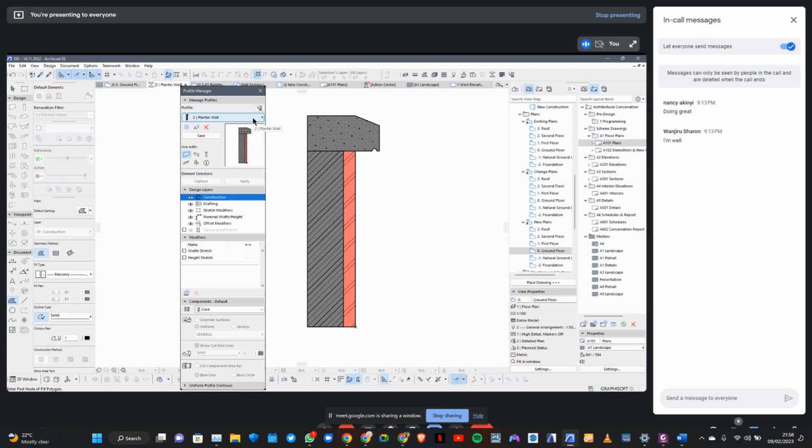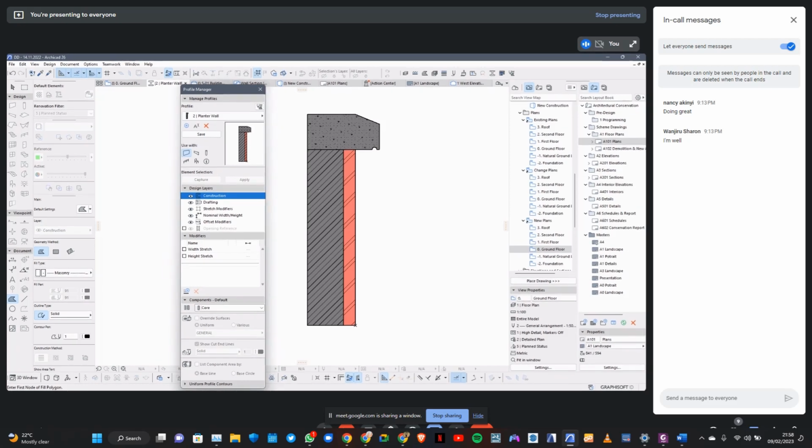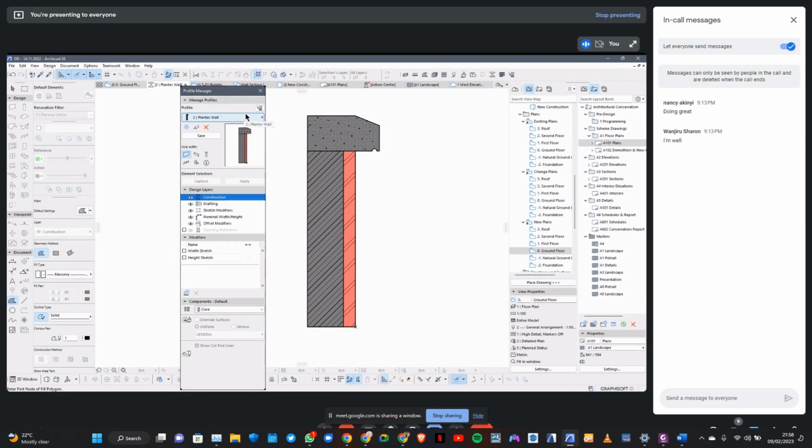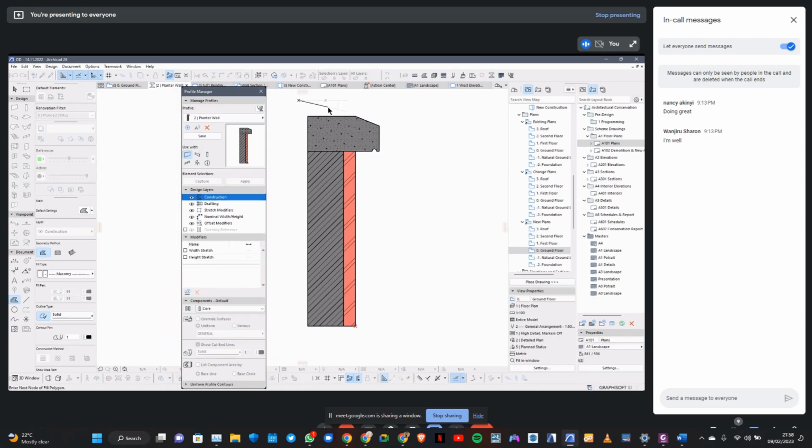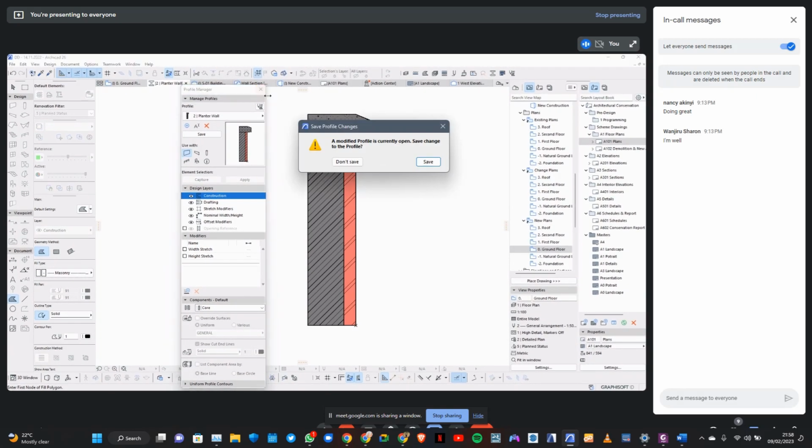I wouldn't want to model every single aspect: draw this wall, then draw another brick facing wall on top, and then try to model the coping using a morph. Because I know how it looks in section is standard, nothing will change about the section. So I can just draw this and then extrude it. The profile remains the same, and the length and shape of the element is what changes. So that's that on complex profiles.